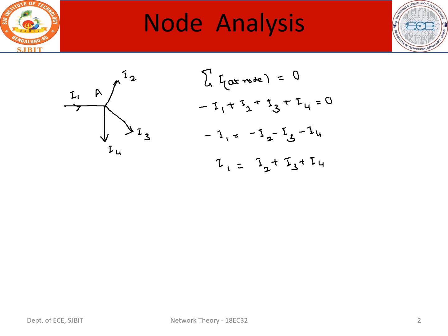This method is used for the analysis of the different nodes of the network, and here one of the nodes will be assumed as a reference node whose potential is assumed to be 0. This is also called a zero potential node, or a datum node. For the other nodes, the different voltages are to be measured with respect to this reference node. The reference node should be given the number 0, and then the equations are to be written for all other nodes by applying KCL.